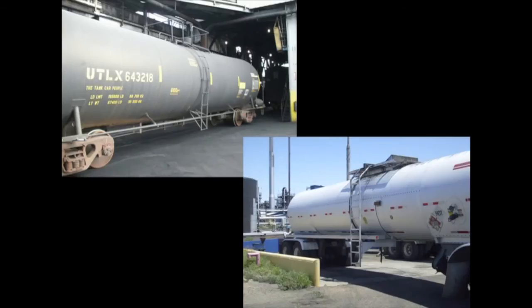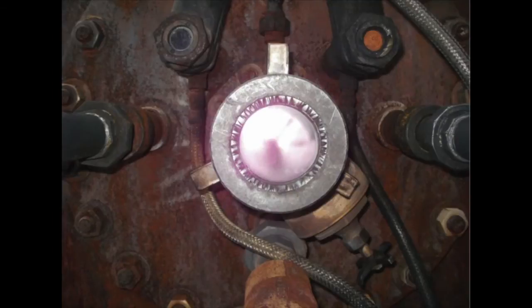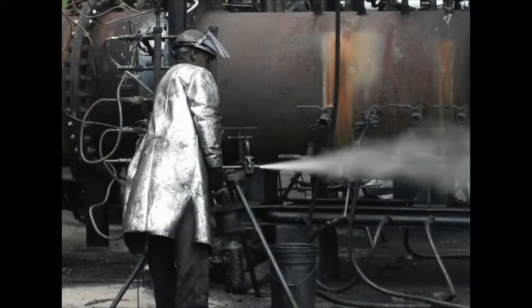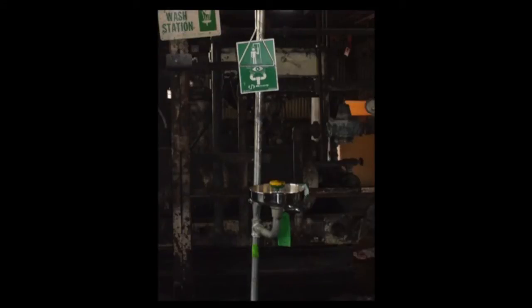Oil is primarily a burn hazard. It has to be heated in order to unload it from rail cars or trucks, and once it's injected into the furnace, it reaches temperatures of nearly 500 degrees. No one is allowed to approach, handle, or adjust oil nozzles unless specifically authorized and properly protected by heat-resistant PPE, gloves, and a face shield. If you're exposed to hot fuel oil, go immediately to a safety shower and flood the area for 15 minutes.